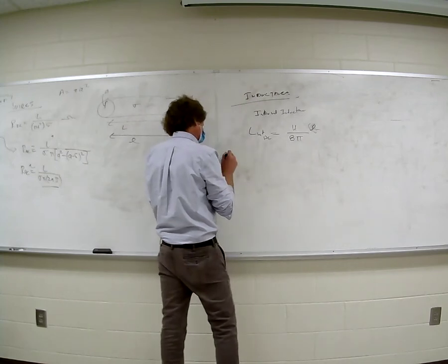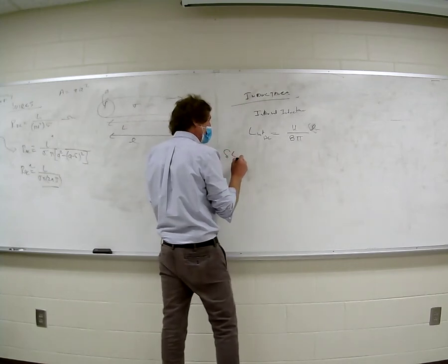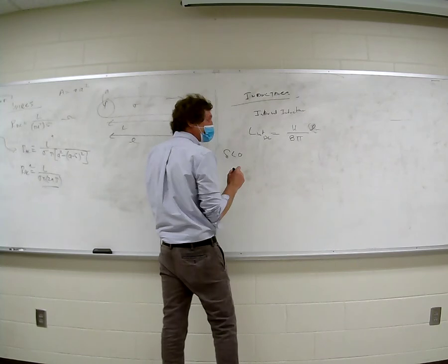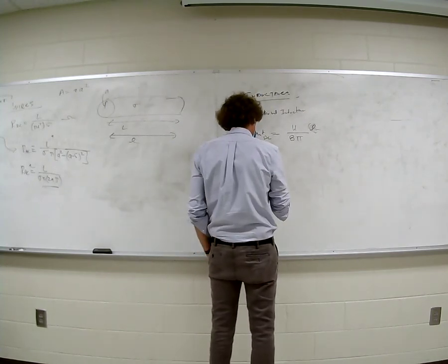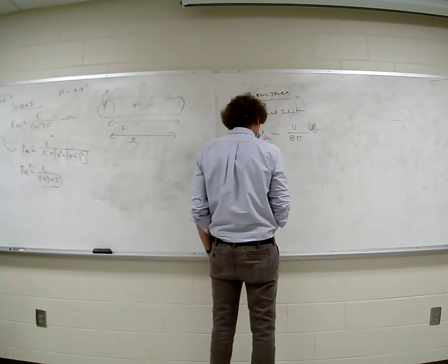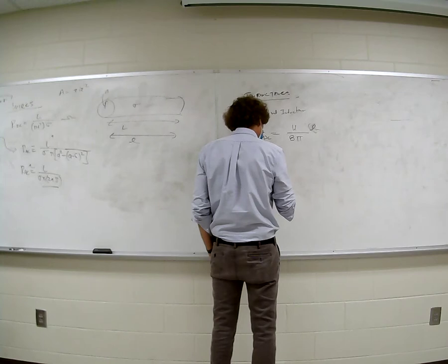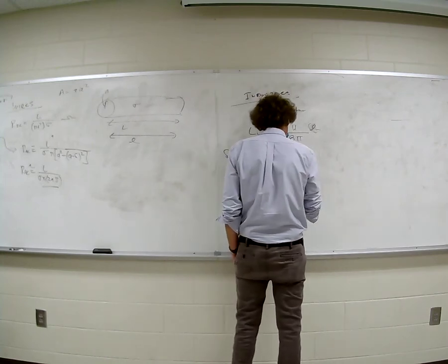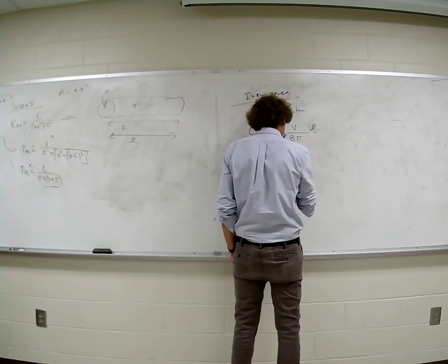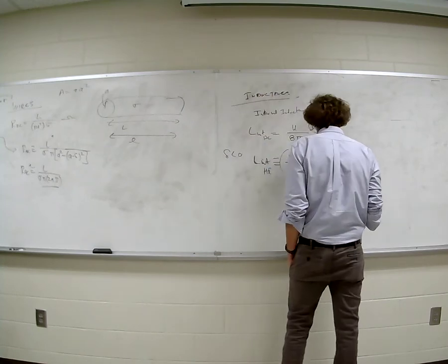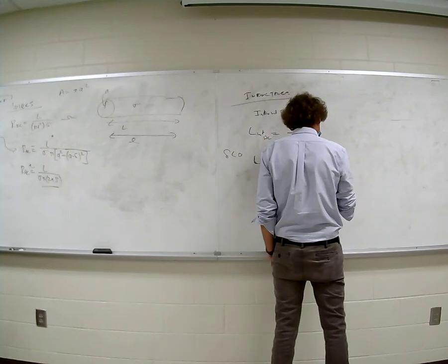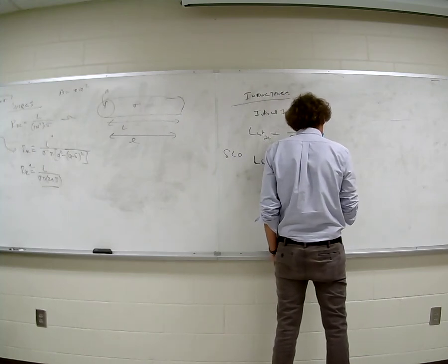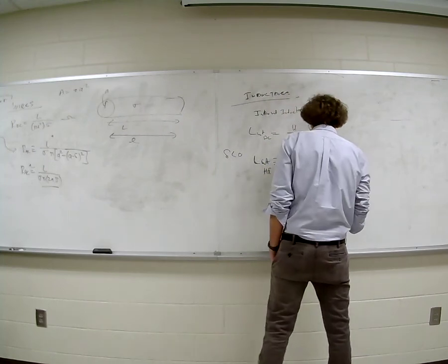That's internal inductance. That's low frequency. Then, if the skin depth is much less than A, then you would say L internal, and what I like to do is call it either AC or HF. HF is high frequency. And it's approximately mu over 8 pi, well, that's the DC inductance, times l, and then there's a factor of 2 skin depth over the radius A.